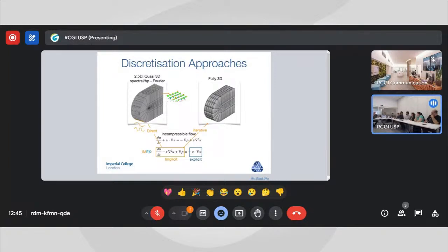But let's say you have a lot of turbulence and you only resolve the first 50% of the spectrum, then you have to worry about aliasing errors coupling back in. But I should point out in the spectral element method that happens in the 2D plane as well. We have a polynomial expansion, and that same coupling happens. And then that's a completely different discussion on how we stabilize these schemes. We tend to use de-aliasing and something called spectral vanishing viscosity, so kill off the high energy when you're under-resolved. But if you fully resolve it, if you increase the number of Fourier modes, it will then run without any stabilization.